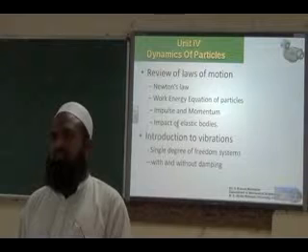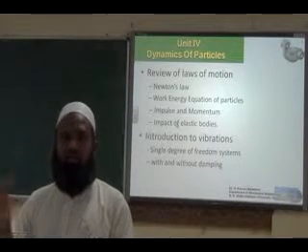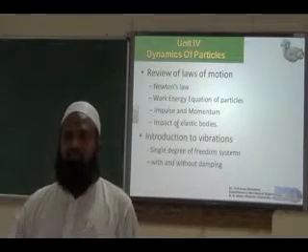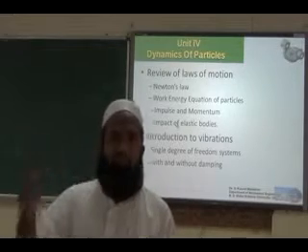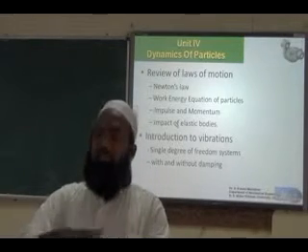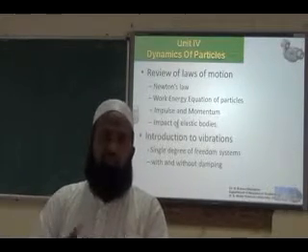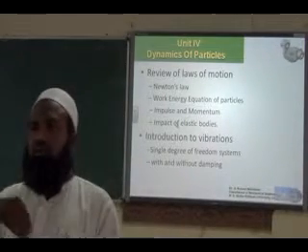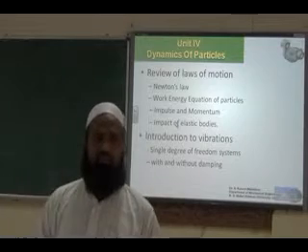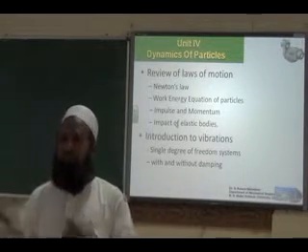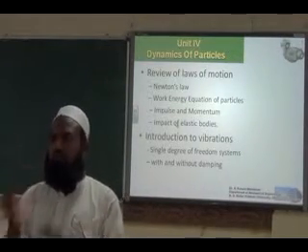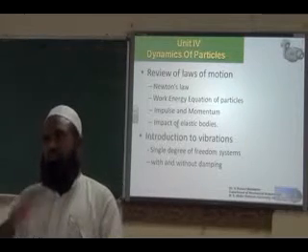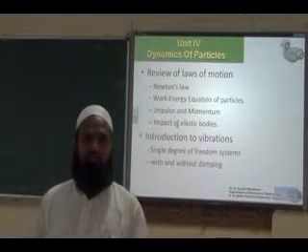You have to pass different machine components to each machine center in a particular orientation. For example, a surface is to be ground, and perpendicular to that surface, a drill hole is to be formed. In that case, you have to tilt your workpiece by 90 degrees. Orientation. We have to orient your workpiece to 90 degrees.